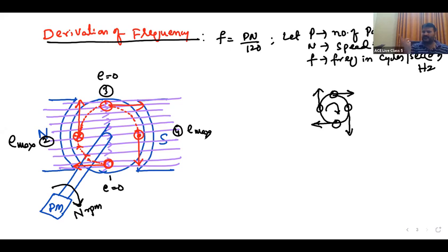Flux direction, motion of the conductor: the current is outwards. It is a dot, coming out from the board, out from the paper. The EMF is maximum. And again, coming to here, the induced EMF will be 0. So the same conductor I have driven through 360 degrees. For every 90 degrees you observe, the induced EMF will be 0 here, maximum here, 0, and again maximum.